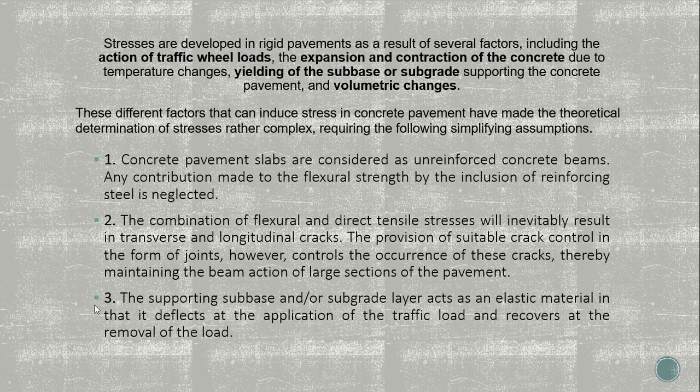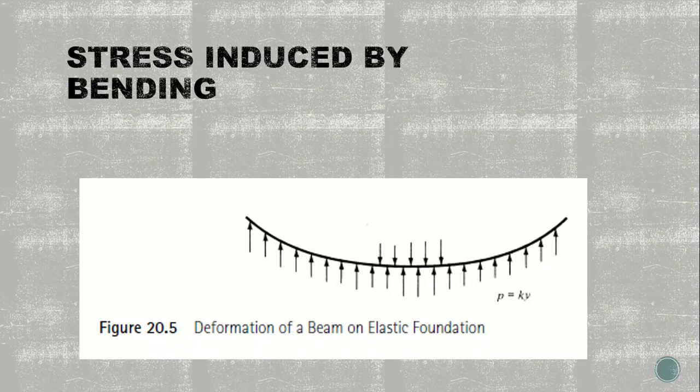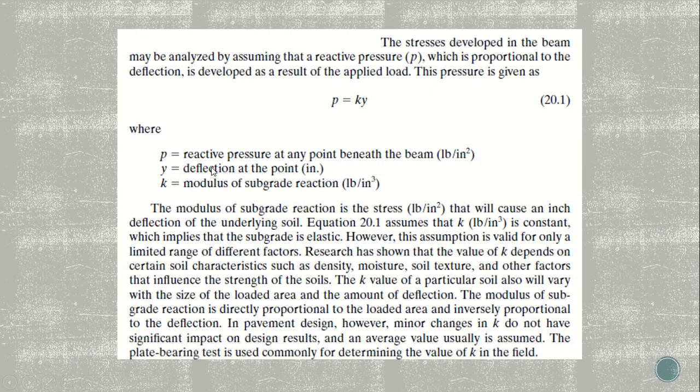The third assumption is that the supporting subbase and/or the subgrade layer act as an elastic material in that it deflects at the application of the traffic load and recovers at the removal of the load. Stress induced by bending. Figure 20.5 shows the deformation of a beam on an elastic foundation. The stresses developed in the beam may be analyzed by assuming that a reactive pressure P, which is proportional to the deflection, is developed as a result of the applied load.